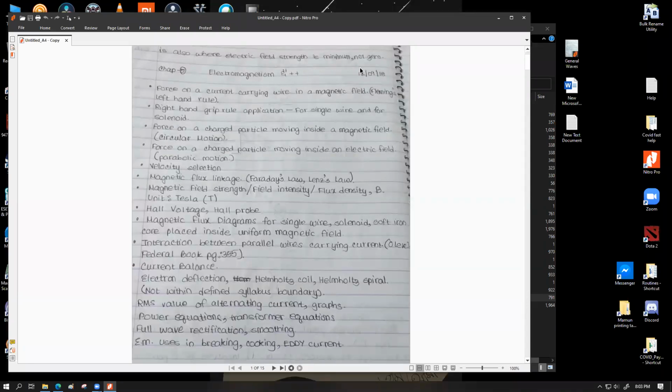It will naturally try to remain demagnetized, but if you bring a magnet close to it, it will immediately become induced by the magnetic field and behave as a magnet. And its magnetism is reversible and changeable, on call for our requirements. If we want this magnetism to exist, we can make it come into existence. If we want it to vanish, we can make it vanish. So we can magnetize and demagnetize it very easily. That's the soft magnetic material, soft magnetism.